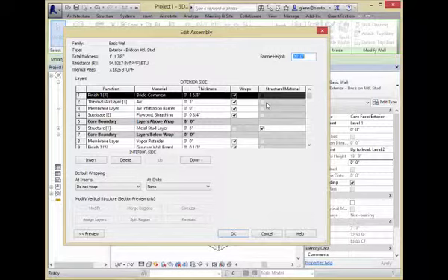So there's something which is called the core. That's the metal stud layer between those two. It's 6 inches thick right now. On top of that, heading towards the exterior side, there's some sort of plywood sheathing, some infiltration barrier, gap for air, and some brick on the outside. And on the inside, there is a vapor retarder and gypsum wallboard. But really, the overall thickness of the wall is determined by all those things. And the thermal properties of the wall are determined by those things, as well as how it's going to render.